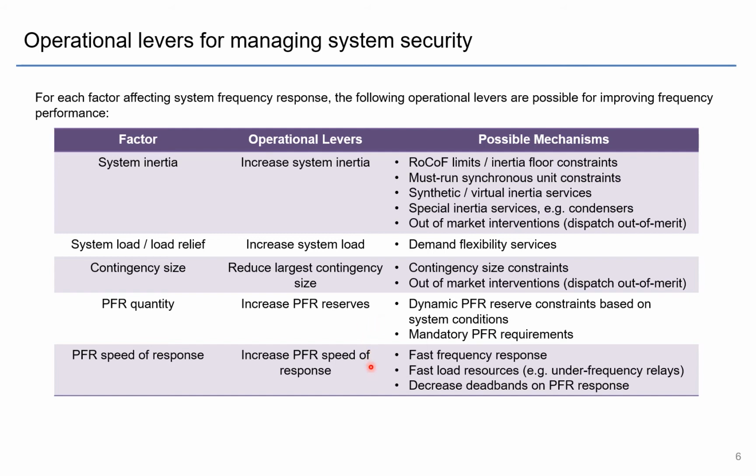And in terms of PFR speed of response, we want to increase the speed of response if possible. And that means we can use fast frequency response services as a possible mechanism, or we can use fast load resources, so those that are tripped on under frequency relays. And also we can just decrease the deadbands on PFR response.